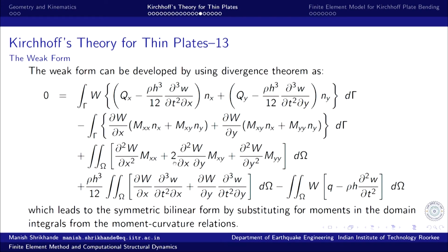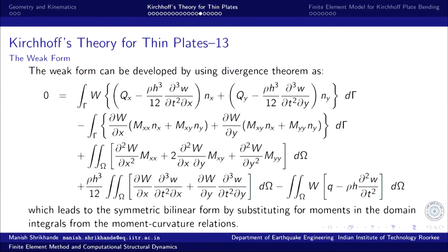Mx and mxy again have highest order 2, since mxx is proportional to the curvature, that is second order derivative again. And then, how many boundary terms are there?